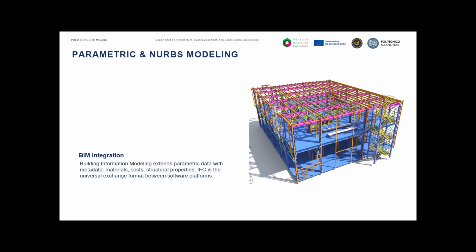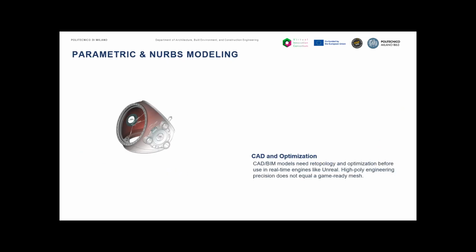This creates a significant challenge for real-time visualization because they export a geometry that tends to be, let's say, poorly suited for rendering. Too many polygons, non-manifold surfaces, most of the times no UV coordinates. So processing BIM data into something that can run in a real-time engine is a dedicated pipeline challenge that we are still developing.